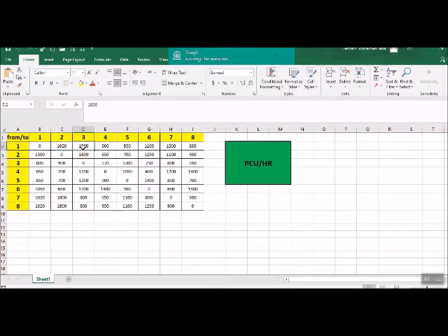The same thing from zone number 1 to zone number 3, we have 1800 passenger cars per hour, and these are the peak hour volumes. And for sure you can get this matrix through the attraction and production that you calculated before between the different zones.